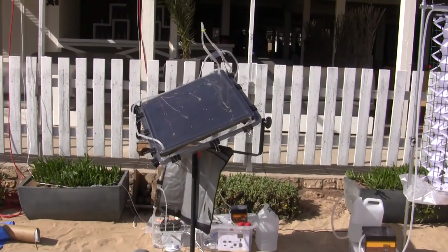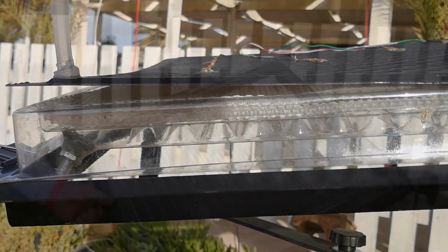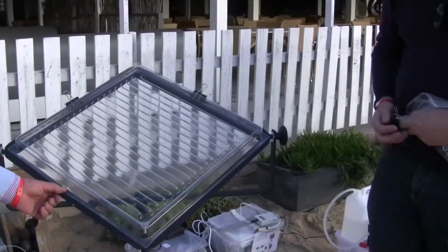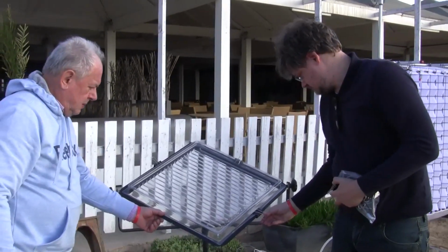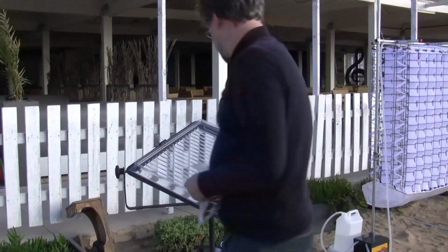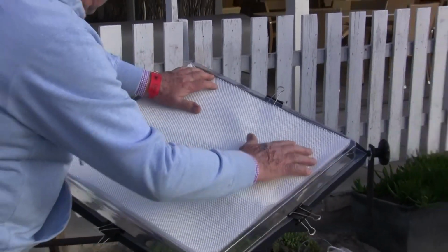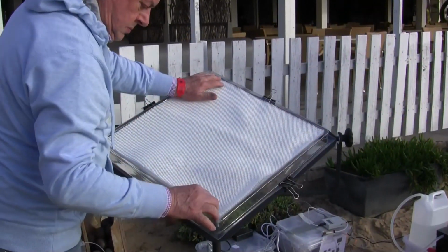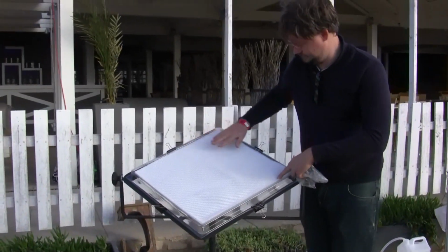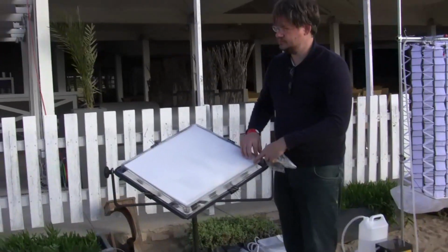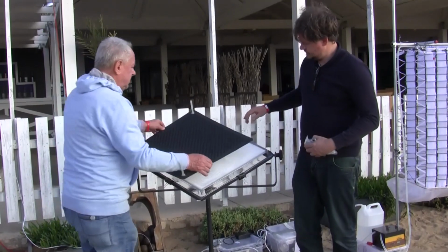This is the extraction unit. It is an enclosed module composed of several layers. From the bottom to the top, there are 4 different areas. The first layer is the condenser, which is cooled by the ambient air from the bottom. On top of the condenser, a thermal isolation layer is added. Then, the sandwich layer, where the hydrated glycerol flows through and is heated by the sun, is placed inside.